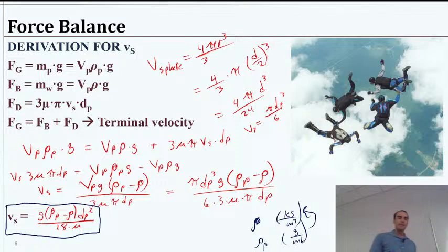But the easiest thing to do would be to change the particle size, especially because that's to a square power, right? Because we are squaring the diameter, and that is affecting our system, that's the best thing we can do in terms of the best increase of our sedimentation velocity given some change in the system.